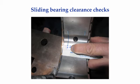Another method is to place a dial indicator on top of the shaft and anchor it to the bearing or machine housing. Then, lift up on the shaft and observe the amount of movement on the dial indicator. Actually, it's recommended to use both Plastigauge and a dial indicator because it's possible that the bearing assembly could be loose in its housing. The Plastigauge would tell you the radial bearing clearance, and the dial indicator would tell you the radial bearing clearance and the amount of bearing assembly to housing looseness.